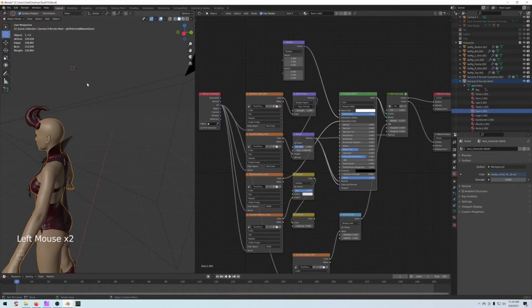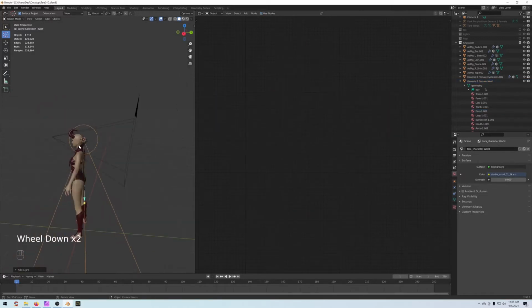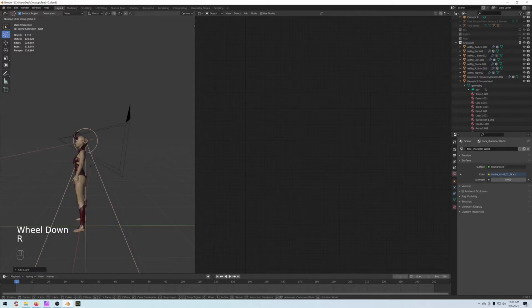And one little trick if you're trying to add something to your scene: if you select the cursor here and click on an object, then when you add our spotlight in this example, it will add it to that location, which gets us close to where we want to be. So we'll rotate on the x-axis, -90.